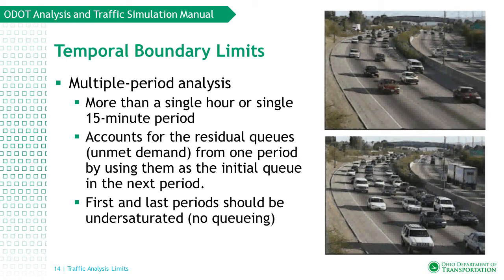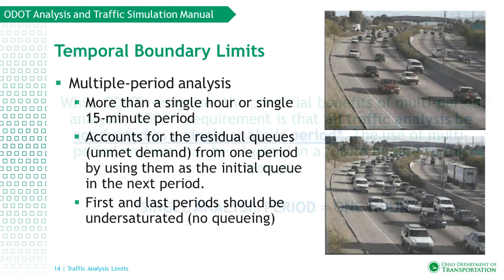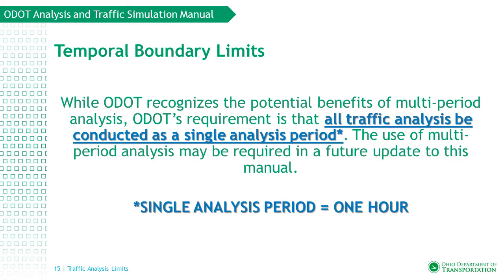It is important to note that in this type of analysis, the first and last periods of the multiple period analysis should be undersaturated. While ODOT recognizes the potential benefits of multi-period analysis, ODOT's requirement is that all traffic analysis be conducted as a single analysis period. A single analysis period is considered to be 1 hour. The use of multi-period analysis may be required in a future update to this manual.